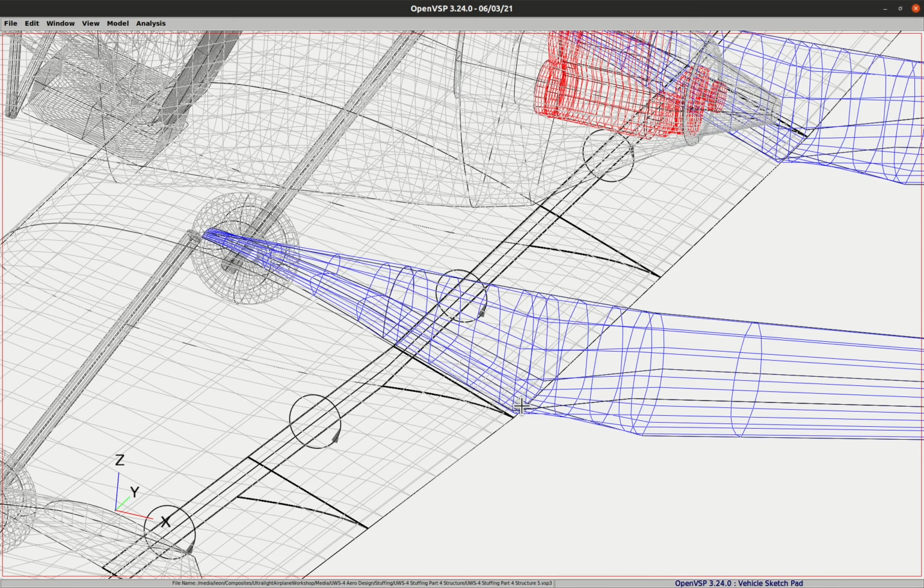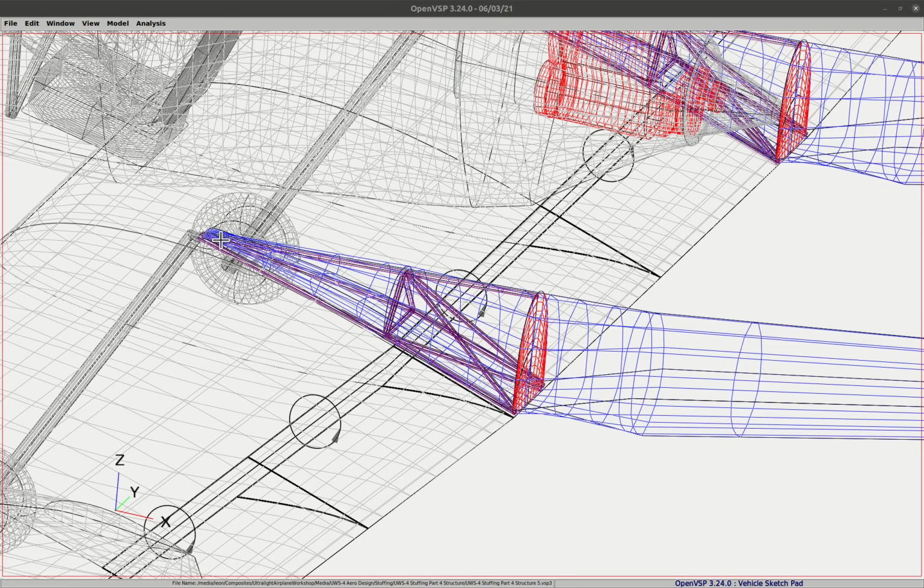I decided to go ahead and add a steel tubing structure in here, and I'll probably cover it with some S-glass fairings because I want to try to fair this in through this area. So let's go ahead and show that. So I've added in here what I think I'll probably do for a tube structure from this area right in here forward. So here are the two rear spar attach points. Here's the front attach point. And then here would be an aluminum bulkhead that would then be aluminum all the way on aft.